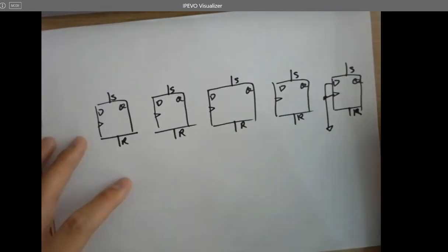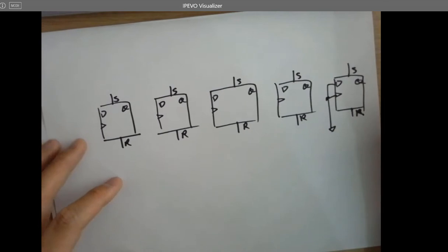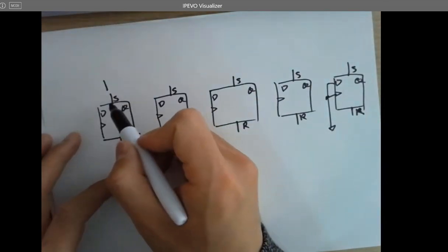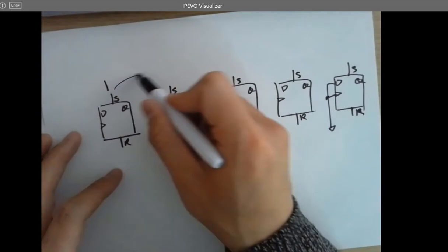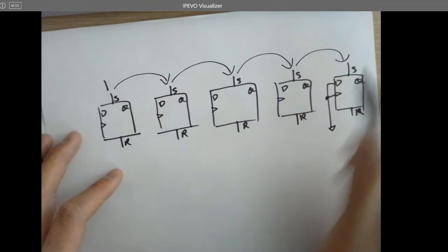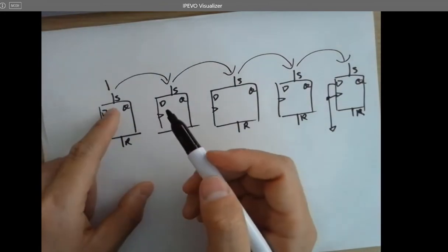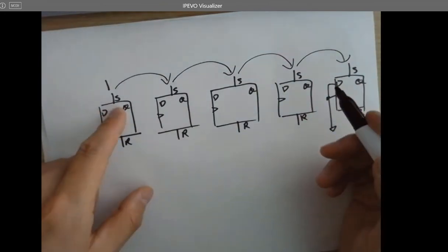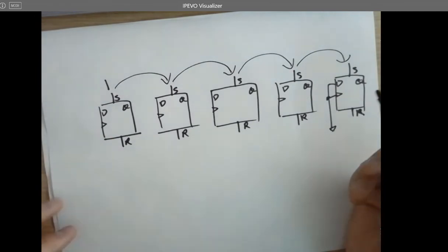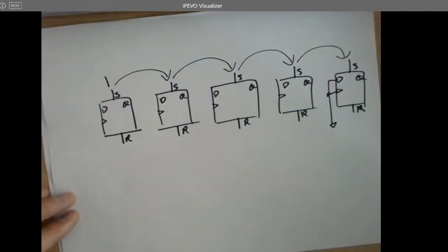And for example, I can assign a 1 to the first D flip-flop and assign the following ones sequentially after every clock cycle. So I'm actually setting every single D flip-flop sequentially like this. But you didn't learn how to set and reset a D flip-flop. It's super simple, and you are going to do it in the homework.